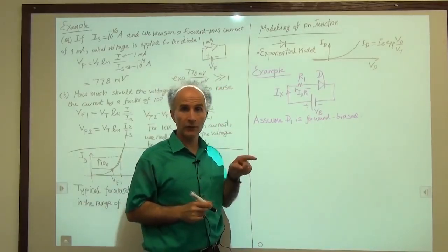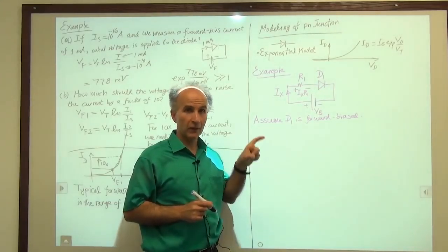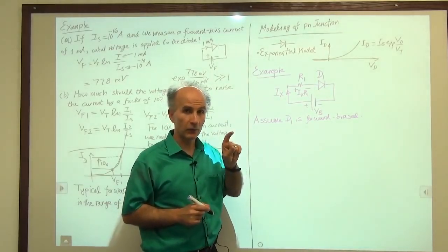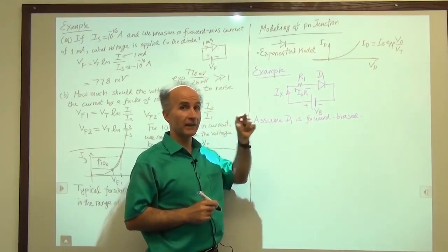That's what Ohm tells us. It says if you push a current from left to right, we generate a voltage equal to that current times that resistor, and that voltage has its positive end on the left and its negative end on the right.